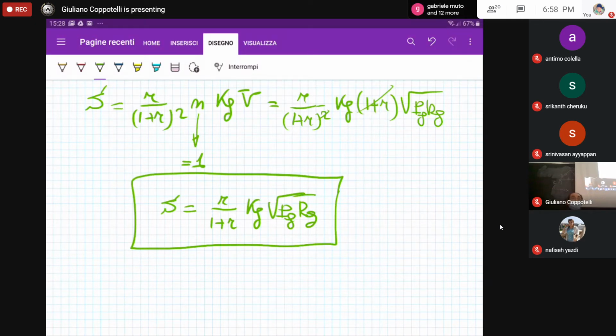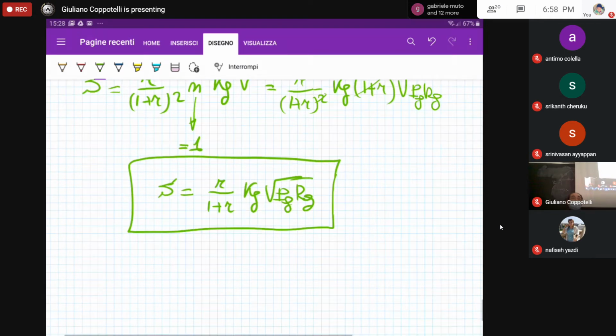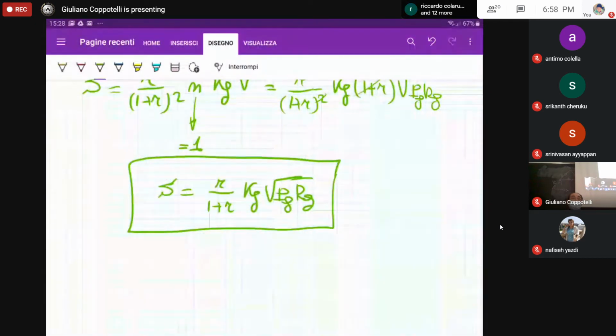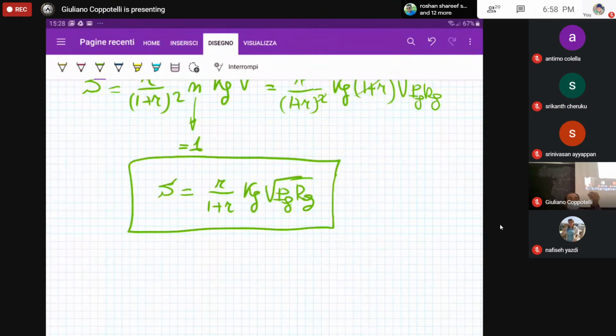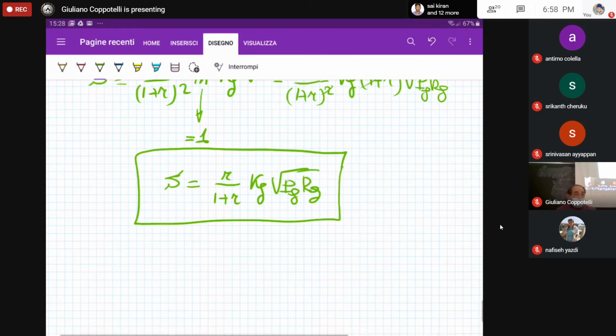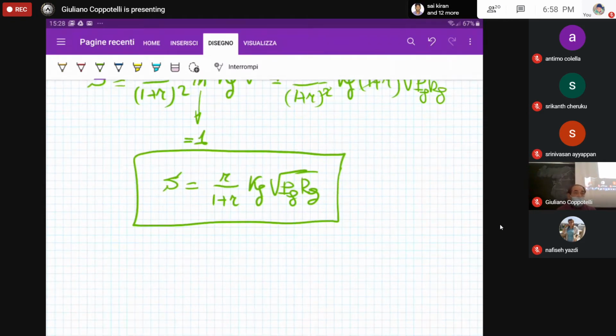Okay, because you can play with the electrical efficiency R over 1 plus R. If you are setting your second strain gauge in leg number 2, then you automatically setting the circuit efficiency equal to 50%. Okay, that's the reason why we are using two strain gauges always in leg number 1 and 4.